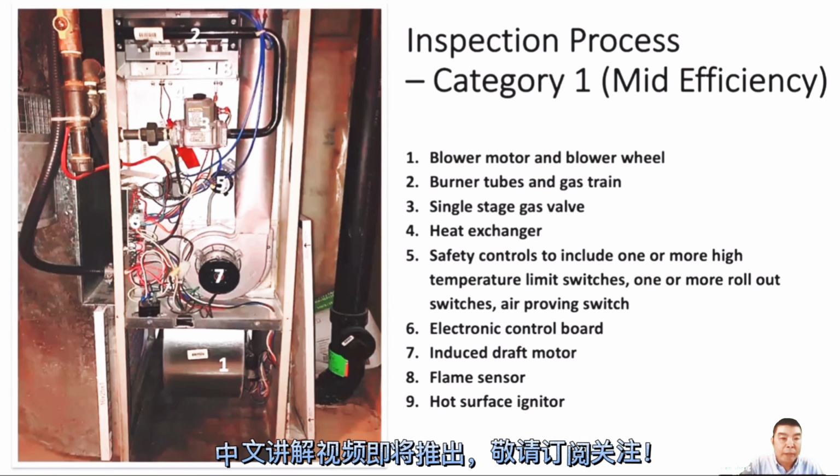It disintegrates the material. If you see white debris, point it out in the report and let the customer know that this igniter may need to be changed to a new one.